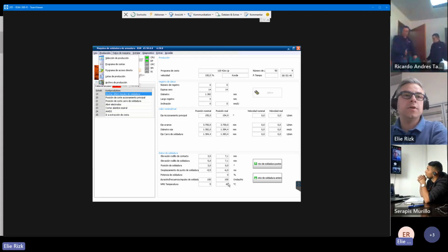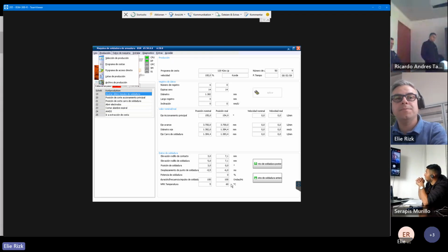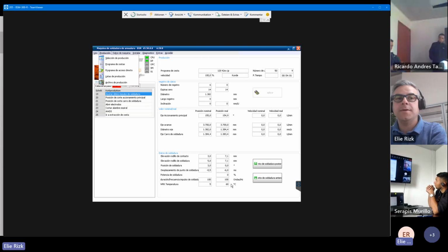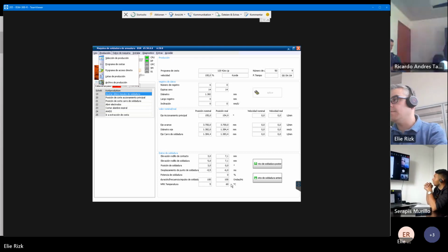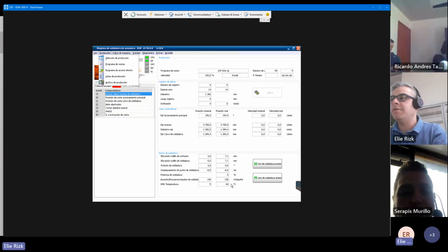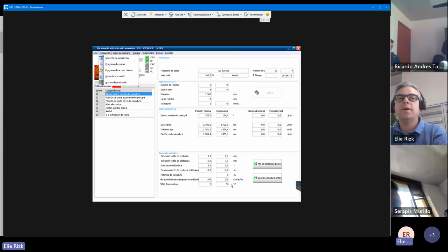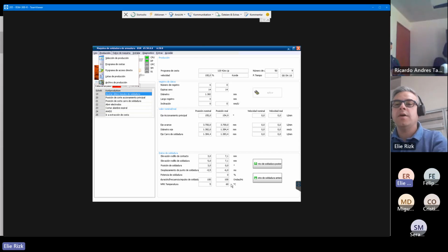But 60 degrees is not a very high temperature, but if the water that is coming to cool down the welding roller is 60 degrees, I think yes, this is a little bit high. It should be maybe a little bit less. You can check the air filter on the cooler. You can check the cooler. You can check the temperature by yourself. Sometimes the temperature reader is not really accurate. Yes, this is what I can say now.